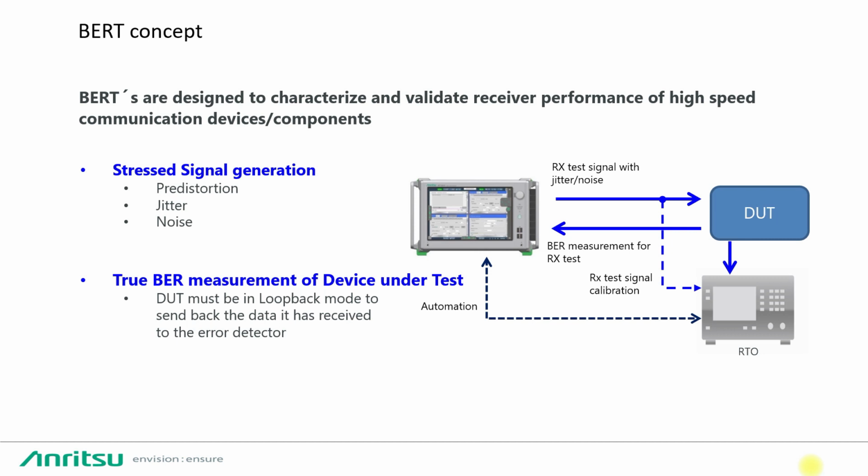On the picture there's a device called RTO, a real-time oscilloscope, which is required for compliance test, but also highly recommended to have next to the error detector to investigate possible pattern sync issues on the error detector.